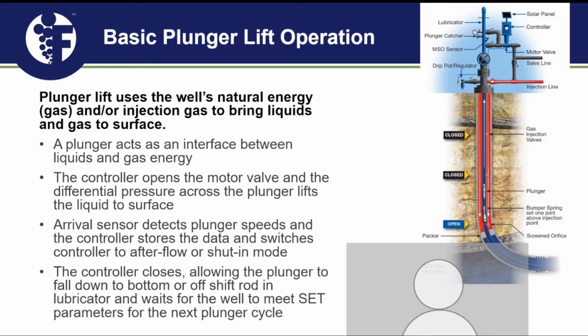Another thing that typically is included with a plunger lift install or system is an arrival sensor. What are those sensors typically? Are they just magnetic electronic switches? Yeah, magnetic, or sometimes they'll sense the density. Okay. And then that's going to be set either on the wellhead or the lubricator, right? When that plunger gets up to surface, that sensor will recognize that arrival and then provide that feedback back to the controller. Right. So, yeah, we'll dive into all that fun stuff.